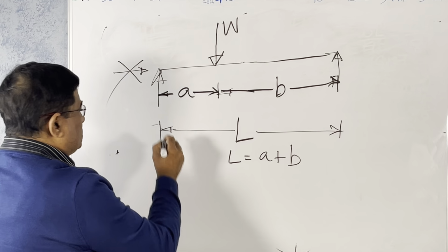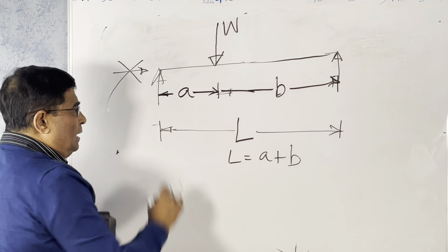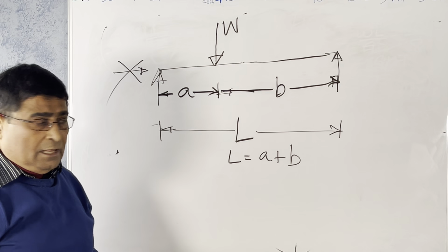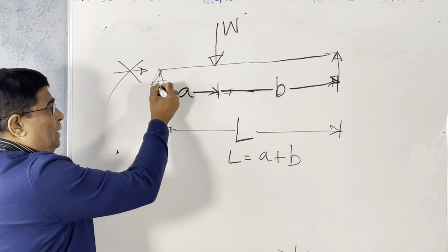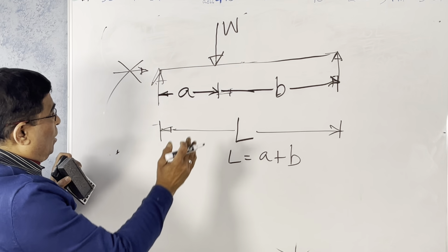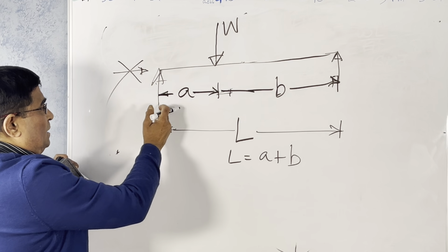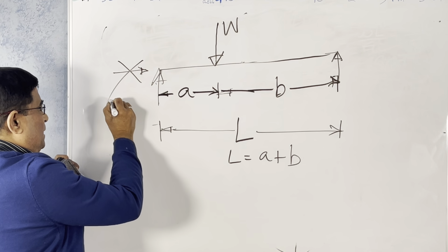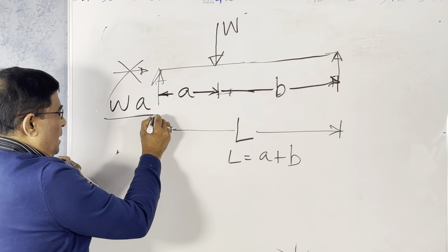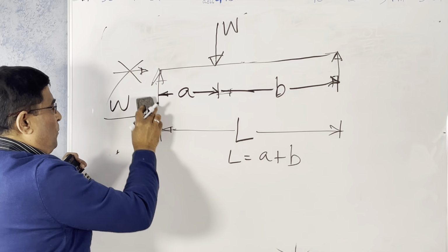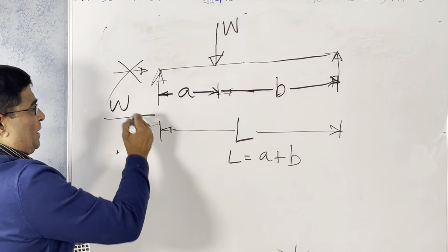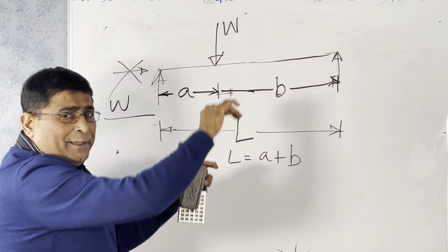Right? So what is the reaction here? Remember, I told you that it is easy to find the reactions. Here the reaction is more, here it is less, because the load is closer to that support. You can write the reaction straight away without taking moment.